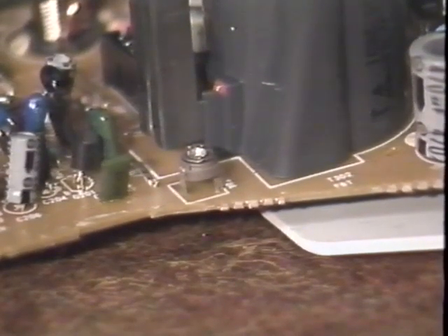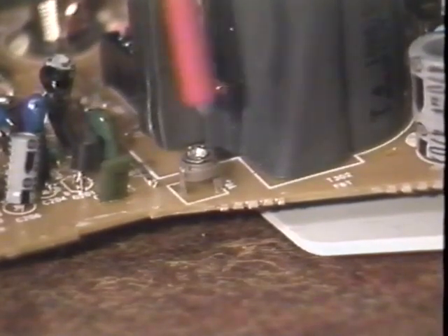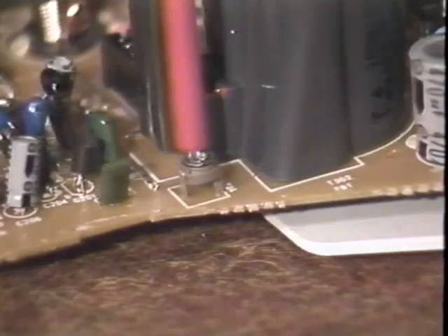If this circuit is not set correctly, the screen may jitter from side to side, be too wide or narrow, or perhaps the characters may not all be the same width. The first adjustment in this series is horizontal sync. If the monitor has an external horizontal hold adjustment, set it to the center of its range.